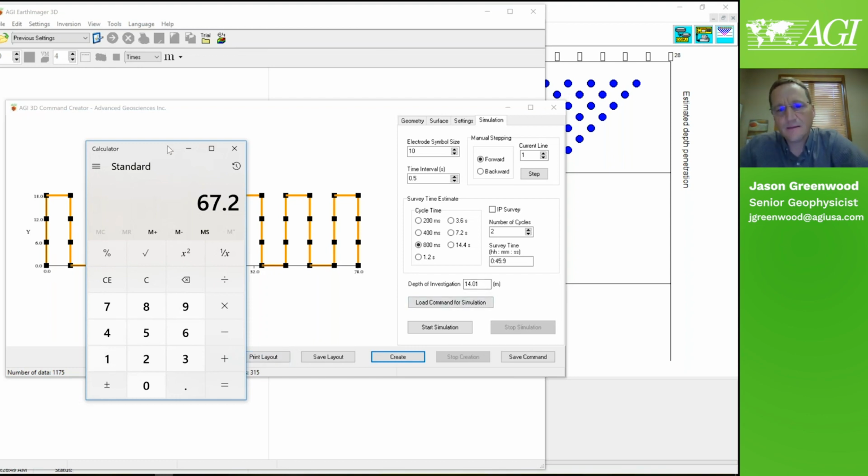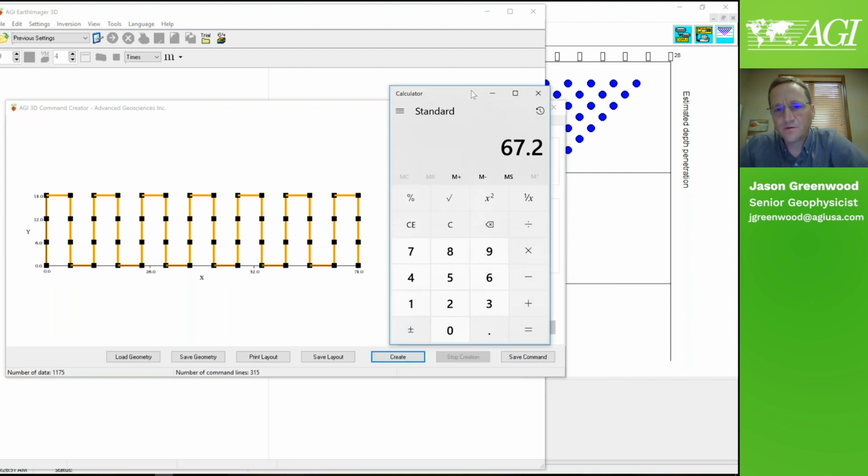So what you're doing is optimizing your resolution to near surface items and in that cross line inline area here. There's a lot more measurements, much denser. So if you have a small target in the near surface and you have the cables, I would definitely recommend 3D.